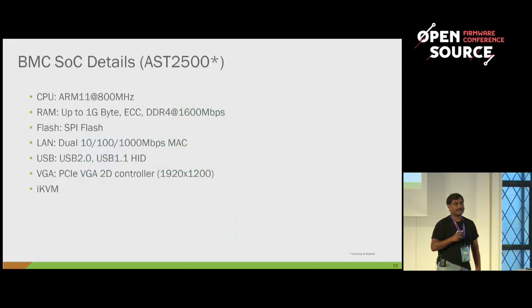And back in the days, the BMC itself used to be very small, like an 8-bit microcontroller. Renesas is one of the famous ones we used to use. And the code used to be pretty much bare-metal code. No operating system, nothing. But in the last decade, I think the BMC became so sophisticated. We started running real-time operating systems like VxWorks, Chorus, and other real-time OSes like FreeRTOS.